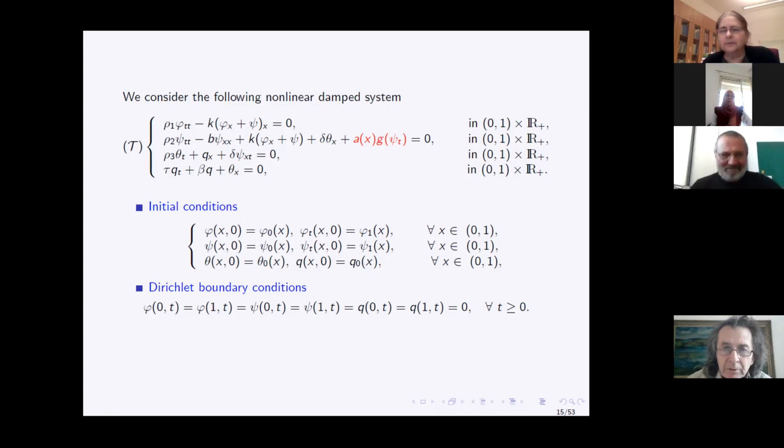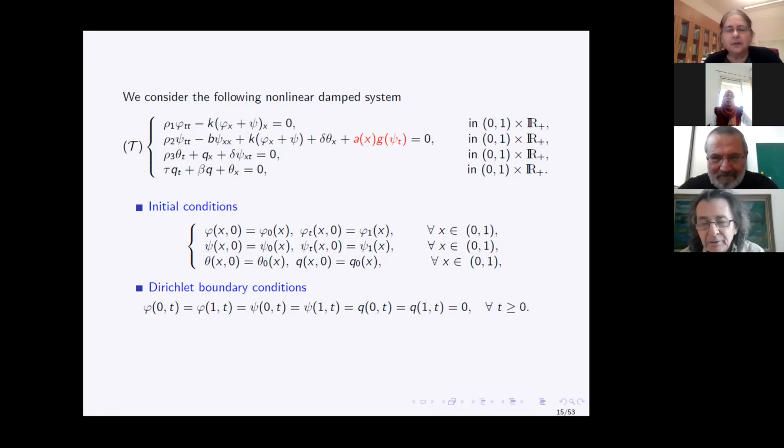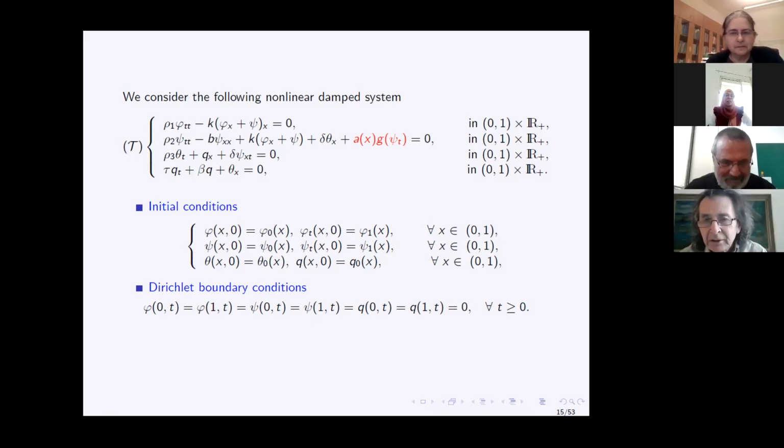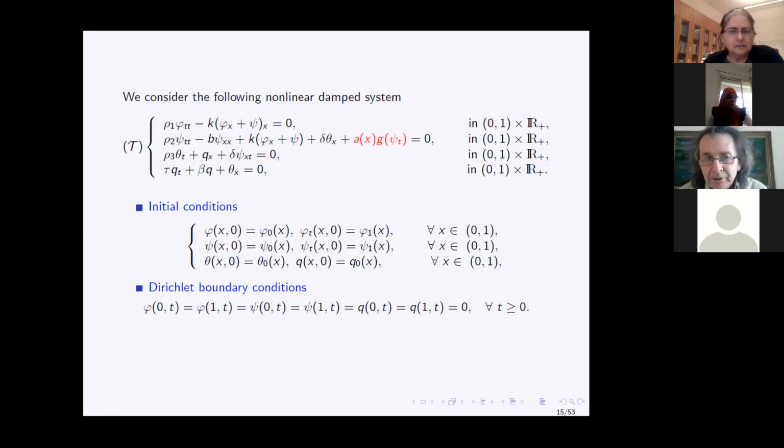Just if I can continue this observation, there is also a problem with the adiabatic heat. The delta term in the mechanical part is some sort of thermal expansion, and then it may go to cooling, and also this is missing. Simply, the system is not thermodynamically consistent, so Pavel has complete right, of course. Okay, thank you.